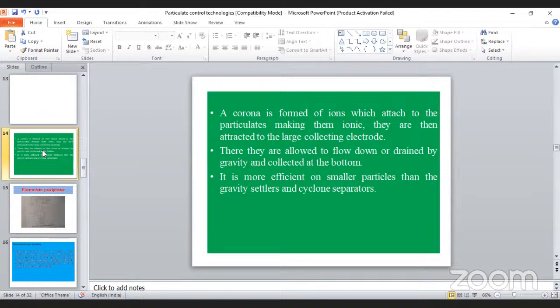So once again, the wire we put inside continuously gets charged. Continuously it is emitting the corona, and continuously when you send the gas stream, whatever charged particles are there in the gas stream undergo the same process of attracting with the corona particles. When it reaches saturation, it becomes inactive. That inactive particulate material settles down at the bottom of the electrostatic precipitator. Then it will be collected.